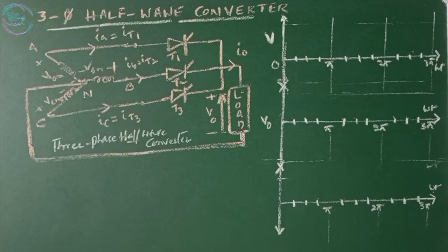converter. The three-phase half-wave converter provides high average output voltage, and in addition, the frequency of the ripples on the output voltage is higher compared to the single-phase converter. As a result, we need less filtering. For these reasons, three-phase converters are used extensively in high-power variable speed drives.